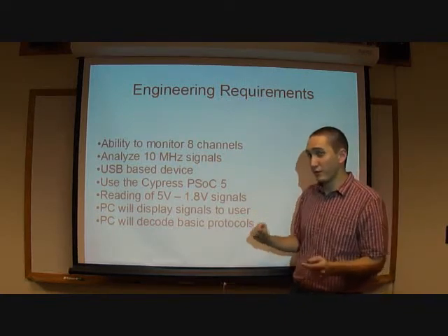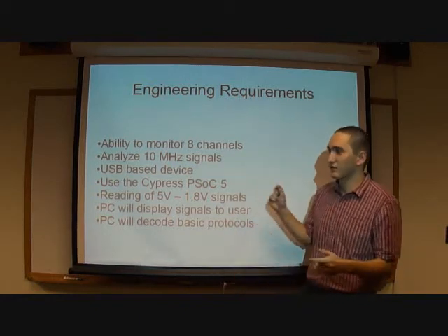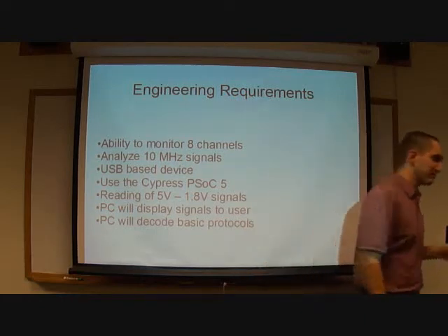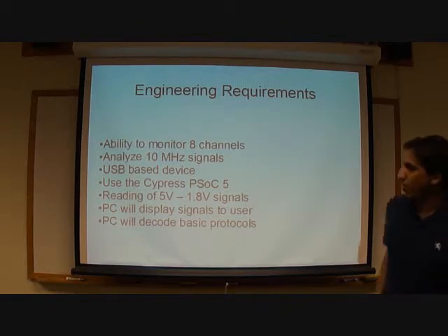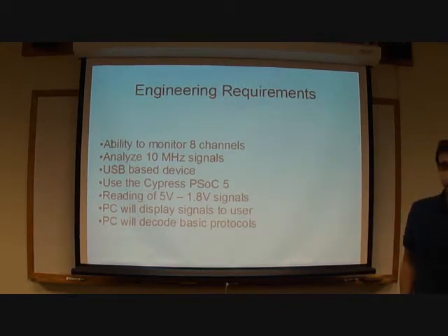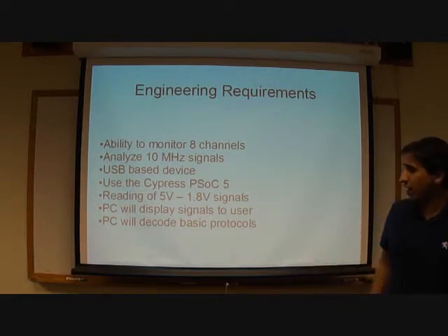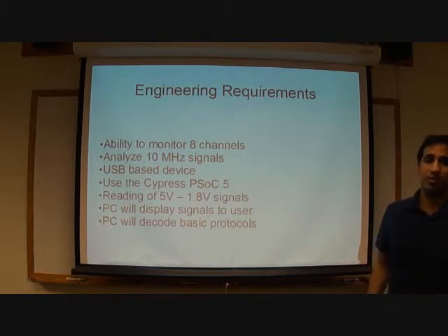It will also be a USB-based device that is powered by USB, and its physical connection back to the computer will be USB. We're going to use Cypress's PSoC 5, which is required by our mentor. We're going to be reading logic between 5 and 1.8 volts. So the user will be able to choose between 3.3 and 1.8 volts.